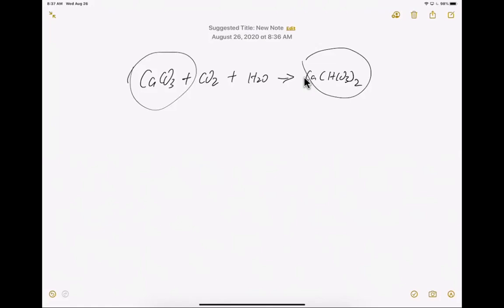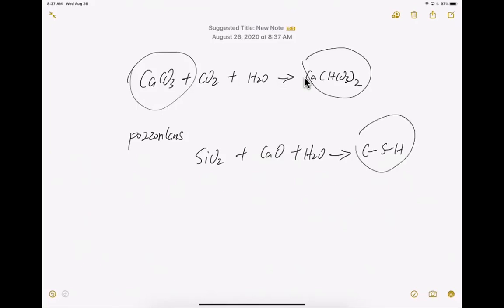But sometimes when we add materials, so-called pozzolans, such as volcanic ash, the major chemical in pozzolans is silica, silicon oxide. So silica plus lime, CaO, plus water, can form a new material called CSH. Okay. So CSH actually is a major component in modern cement, and the strength of CSH is very strong. Okay, so